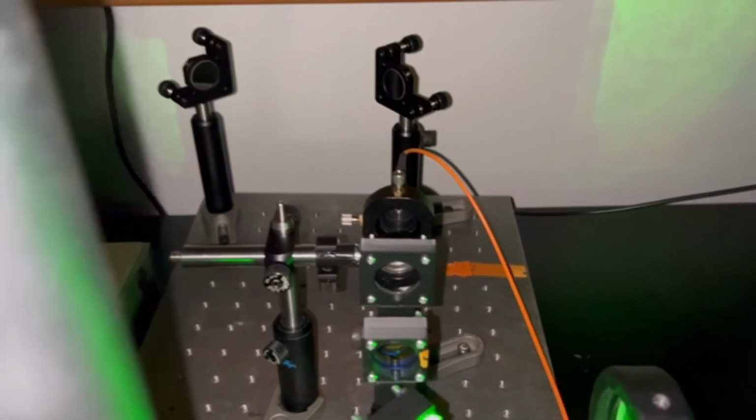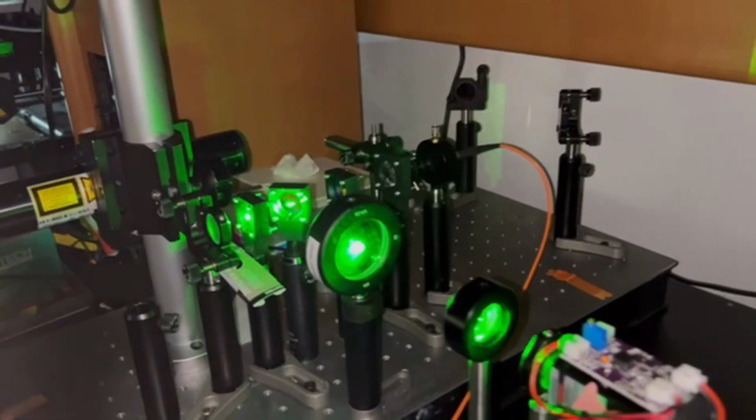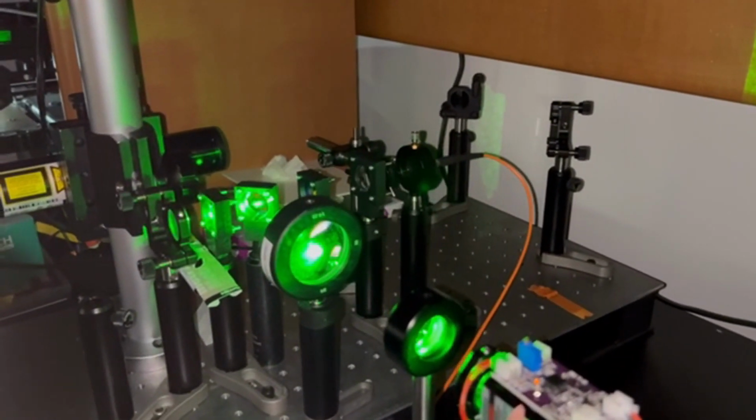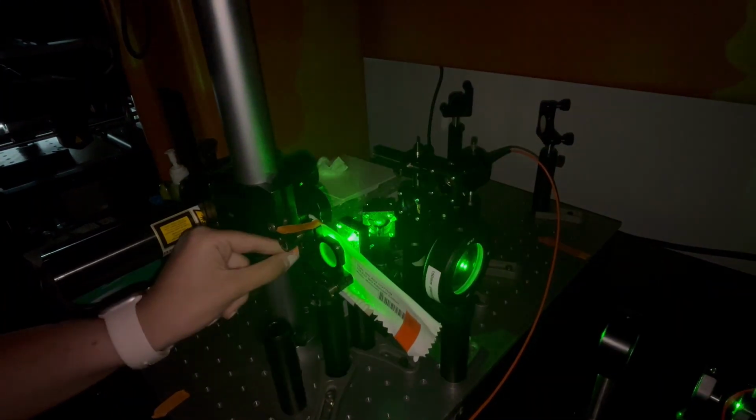A 75mm focal length lens couples the signal into an optical fiber for the blue wave miniature spectrometer. In the final system, our custom-built spectrometer will take the place of this fiber. Using this test setup, we collected data from an ISO-adjacent cotton sample 3 times and recorded the spectrum each time. The integration time used for each trial was 10 seconds, keeping in mind that our engineering specifications stated we should have an overall system response time of 15 seconds.